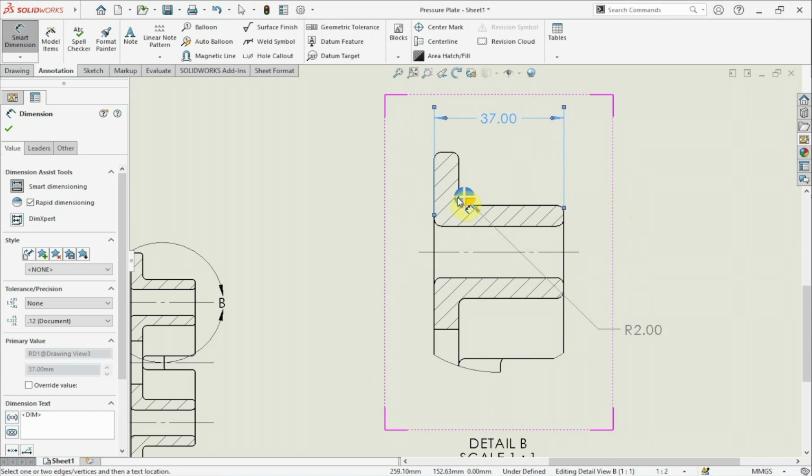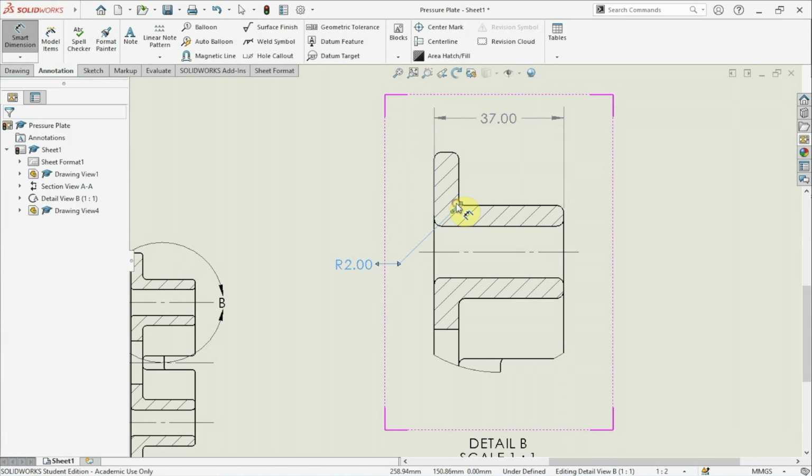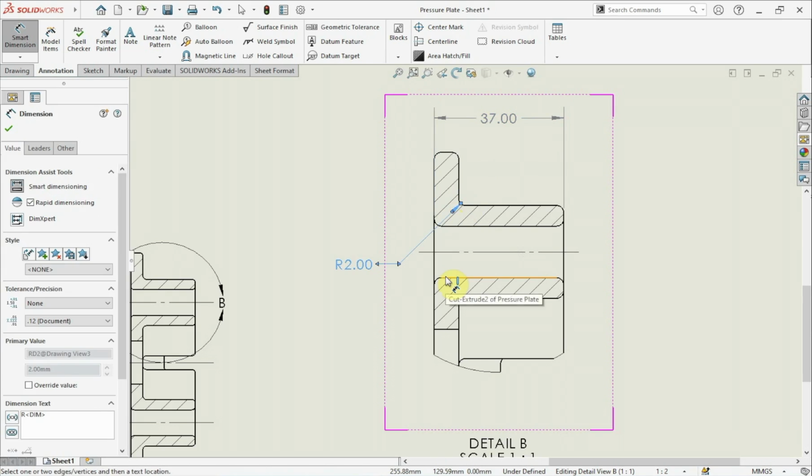And next up, you want to do this fillet here. And it's going to apply a radius because fillets are roundings. So we want a radius of 2, or it's going to make a radius of 2 right here. And we just want this length between this line and this line. So let's go ahead and do that. Click on this line and this line. And there we go. We have basically a little space of 7.